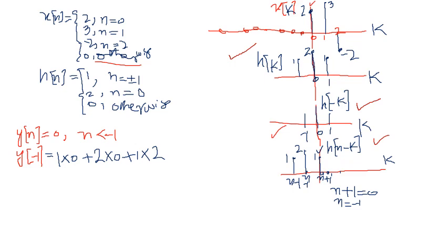This is 1, and this is your original signal, equal to 2, so 1 into 2, whereas here the signal is 0. Again at this position this signal equals 1 and this signal equals 0, so I wrote 1 into 0. I hope this gives you an understanding of how we are calculating the convolution sum. So that means it will result in 2.